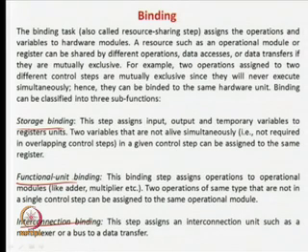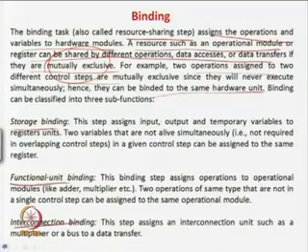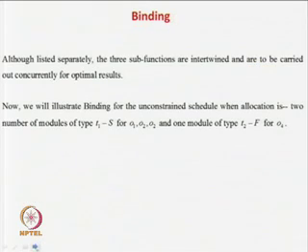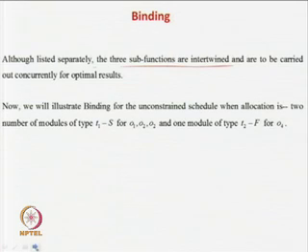That is, which hardware will do which operation, and similarly, interconnect binding is the actual use of multiplexers and wires. So, that is about the three types of binding, which we will illustrate by an example that you are already using. As already said, there are three different binding steps, storage, function unit and interconnection binding. They are written as three different steps in all texts, but actually they are intertwined and done hand in hand.